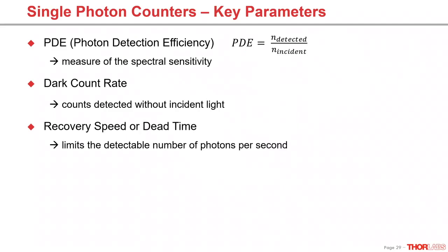The recovery speed or dead time is the time to re-trigger the system. That means until the electrical field has rebuilt. At that time, no photons can be detected. The dead time is in the single nanosecond to hundreds of nanoseconds range.